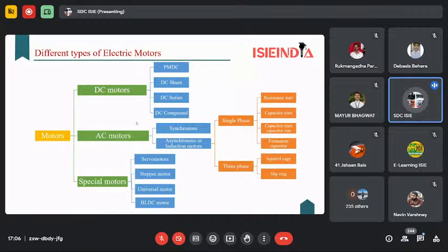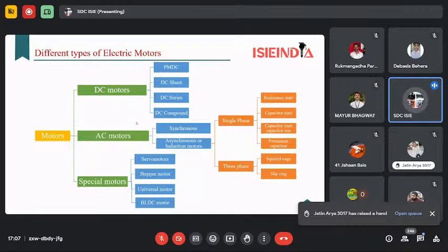And one of the motors is a BLDC motor, a motor with a DC configuration, but it does not provide a power supply to the rotor, and it works the same as a synchronous motor. It works on the response of the Hall effect sensor present on the motor. It will not work without the controller. We'll see that special technique in the upcoming slides.